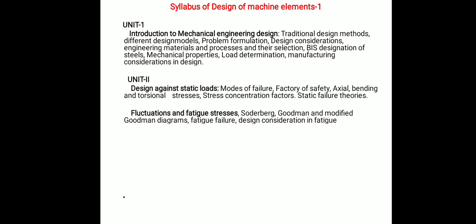We will see design against static loads. In case of design against fluctuating loads, most of the components, whatever we are saying in our day-to-day life, are subjected to stresses like a repeated loading. If you take the actual service conditions of any mechanical component, then no component is subjected to a static loading condition. Therefore, determining the dimensions against static loading is very simple based upon the elementary equations.